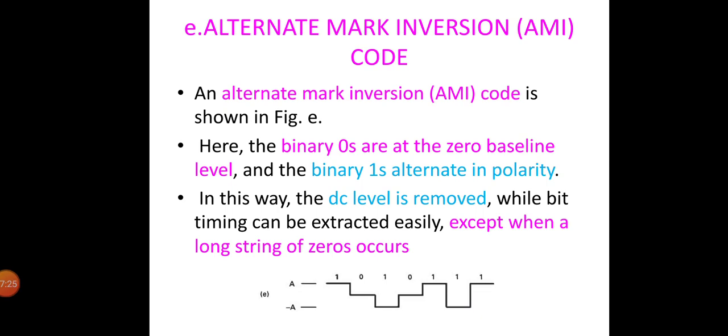So, this is referred to as quaternary encoding, and the waveform is shown. The encoding is symmetrical about the zero axis. The spacing between the adjacent levels is 2A. And each level represents a symbol, the duration of which is the symbol period. For the quaternary waveform, the symbol period is seen to be equal to twice the bit period, and the symbol rate is R symbol equals 1 by T symbol. The symbol rate is measured in units of bauds, where 1 baud is 1 symbol per second.